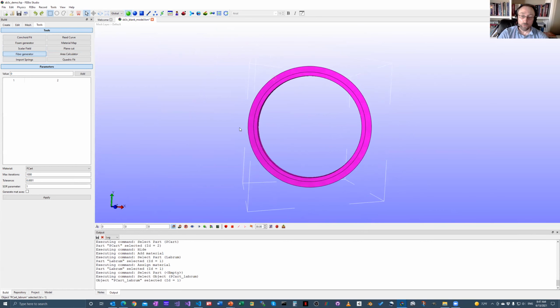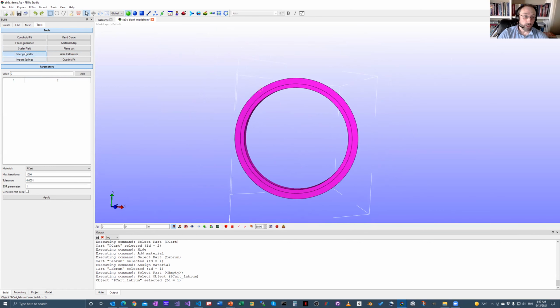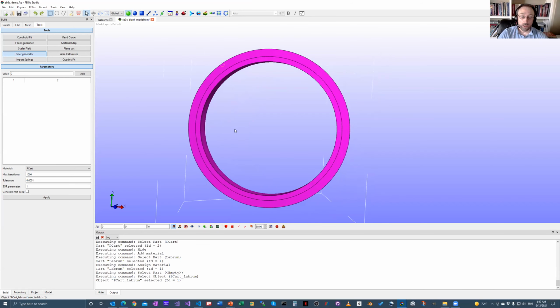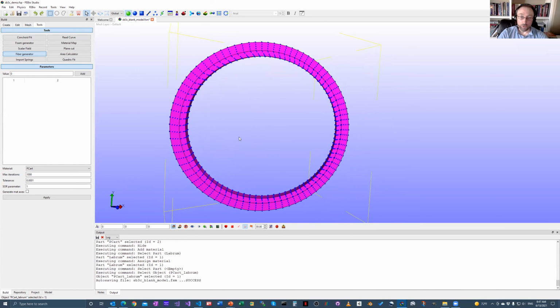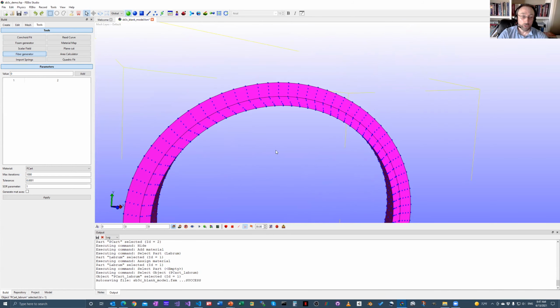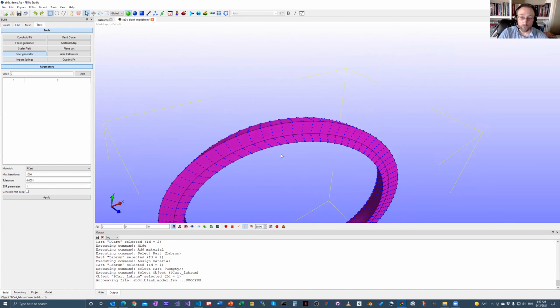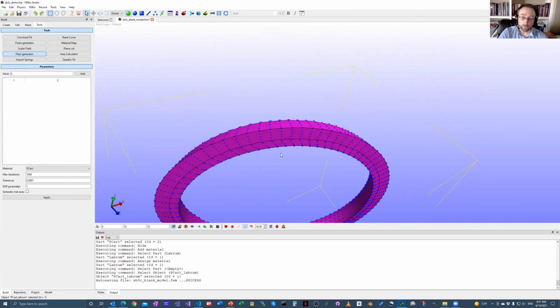So the way this tool works, first of all, it's going to generate a scalar field as it did before, but in order to generate the fibers, it's going to take essentially the gradient of that field and assign that to the fiber property of this material. So how do we do that? Well, the way we're going to do this is we're going to create, as before, some boundary conditions for our Laplace problem. In this case, we're going to select some nodes.